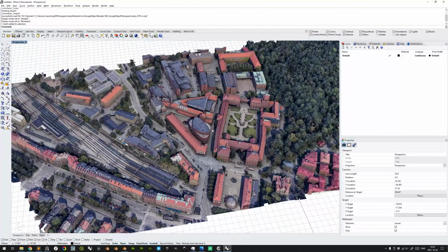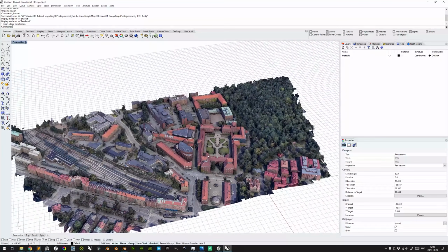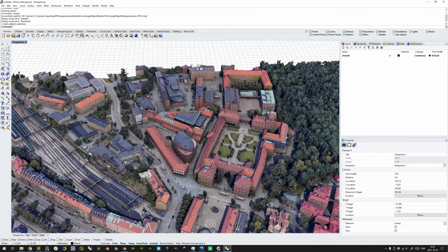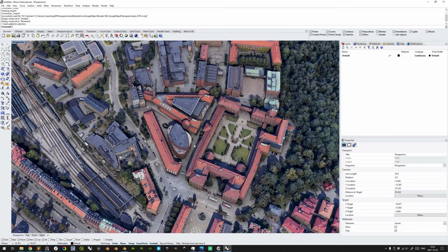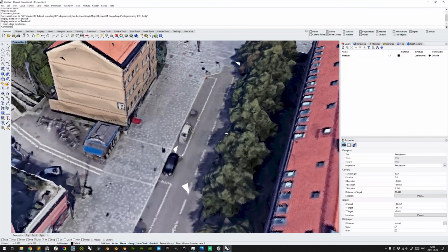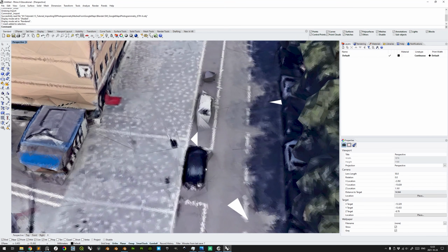But this can be, of course, fixed here in Rhino if you have a reference, like the buildings represented by building blocks downloaded from the Stockholm municipality, or if you have building footprint curves downloaded from SLU, Geodata Extraction Service, or anything. Then you can scale it. Yes, now as in this tutorial, perhaps we can scale it like this car. We guess it is approximately 1.9 meters over here.